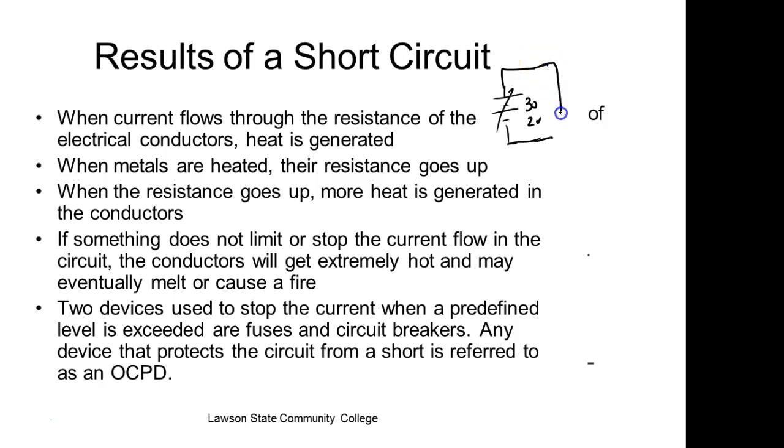And I'm going to come over here and put a wire there, and the wire's going to start getting hot. Well, as soon as the wire starts getting hot, its resistance goes up, but this power supply is trying to regulate it at what? 30 volts, so it'll go up. And it just cascades after that. So eventually all the insulation will burn off the thing. We might move it over to the classroom next door and give it time for the smoke to clear. But all the insulation will disintegrate off the thing. And then once your insulation is gone, and if you've got multiple conductors inside that raceway, then you got big problems, right?